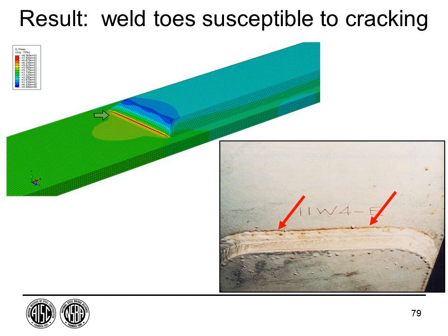average daily truck traffic, right? So that's usually how they report it for convenience, as a percentage of the daily traffic. The thing you really want to make sure of when you get the ADTT numbers, no matter how they got them, is what are they giving you? I've learned over the years that traffic people tell you the truck traffic's 1,000, and then you find out that that was for both directions. So it's 500 one way and 500 another, and you have two twin interstate bridges. Oh, well, now I'm off.